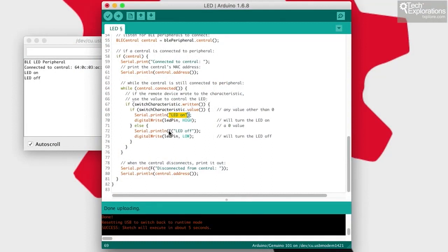And on the Arduino side, you can simply use the library that comes with the Arduino 101. On the phone side, depending on whether you are using an iPhone, iOS, or an Android, or some other type of device, even a desktop computer, then you need to use the libraries that come with those particular platforms in order to implement this type of functionality. But you can experiment with the Nordic Semiconductor apps as you are designing the application, at least on the Arduino side. Let's move on to the next lecture, where I'll show you a couple of other BLE-related sample sketches.